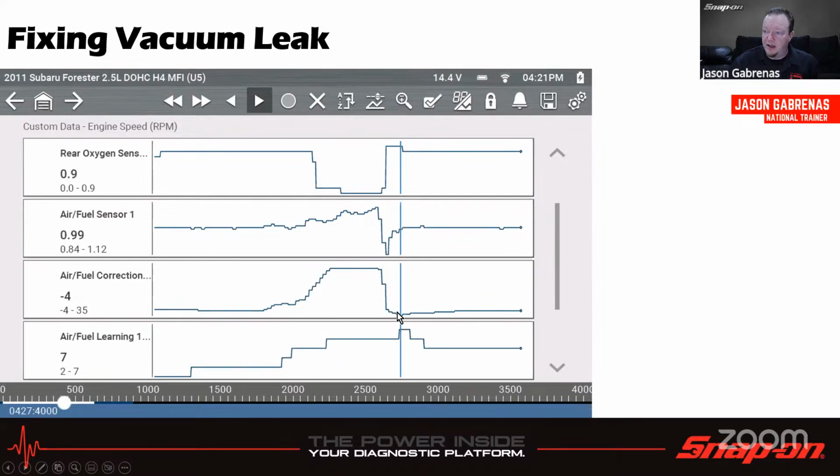And then due to that, our short-term fuel trim goes negative, but you can see our long-term fuel trim was still going positive because it lags that much. We had plus 35% for a while. So it says, oh, well, I guess I got to adjust again because we're plus 35%. But over that time, things have adjusted, but you can kind of see that offset between the short-term reacting quickly and the long-term not reacting quite as quickly. And then over time, it slowly adjusts and goes back to where it was once the repair is complete.